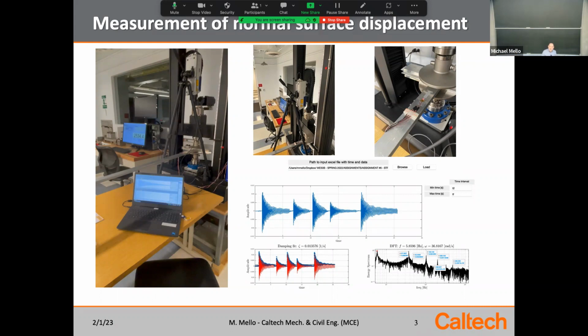You glue a strain gauge to it, and as long as your data acquisition equipment is fast enough, it'll keep up with those oscillations. It'll report to you whatever the vibrations that the strain signal picked up. And actually, strain gauges turn out to be an excellent way, as we'll see. The vibrometer is exquisite, though. It has a higher fidelity. It has a finer resolution.